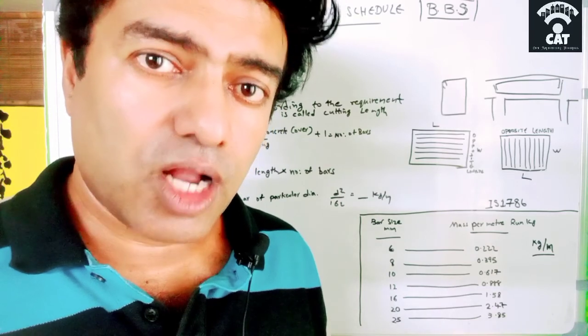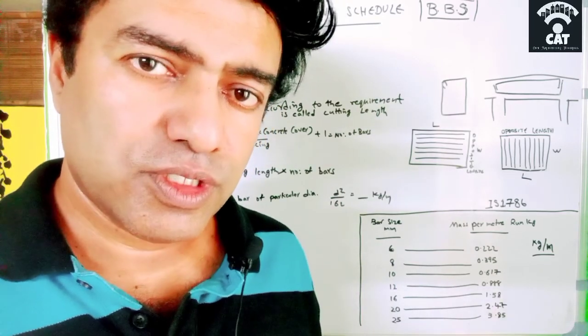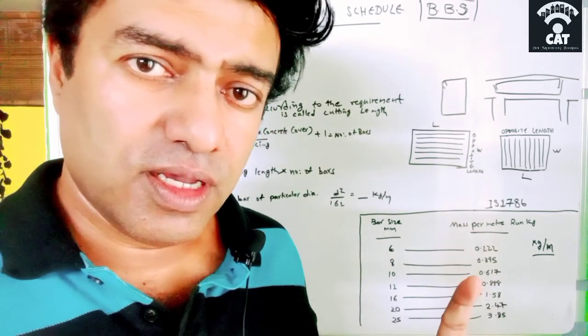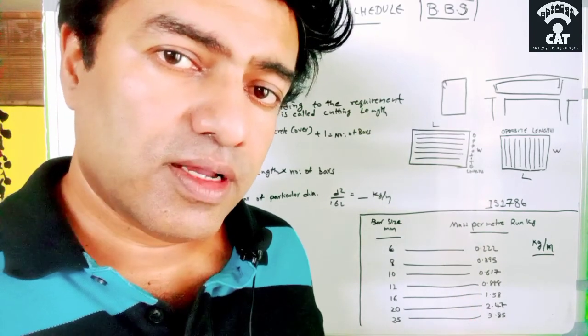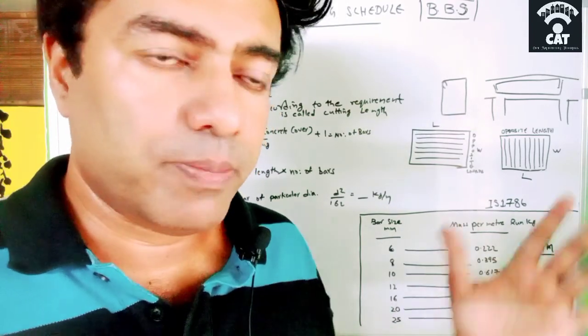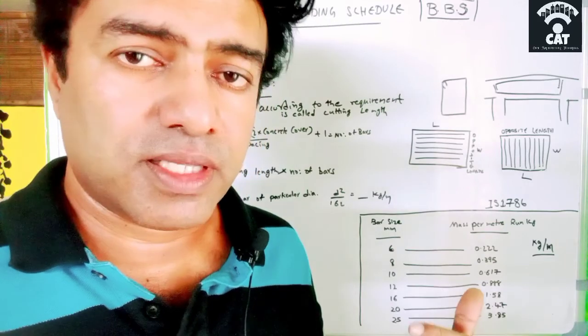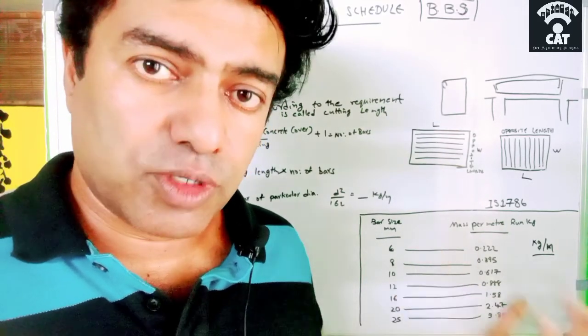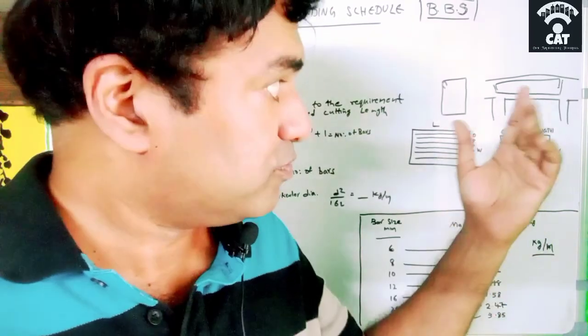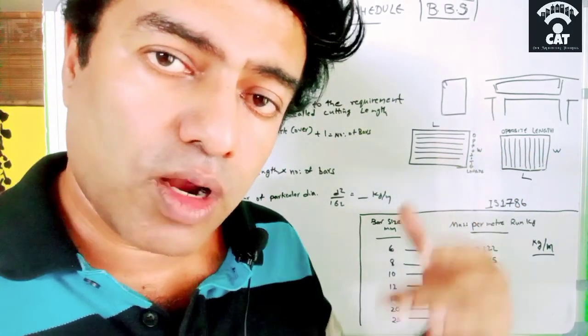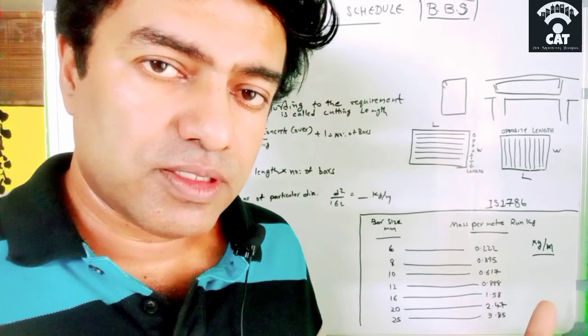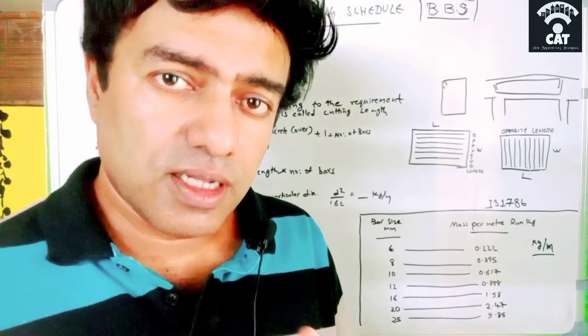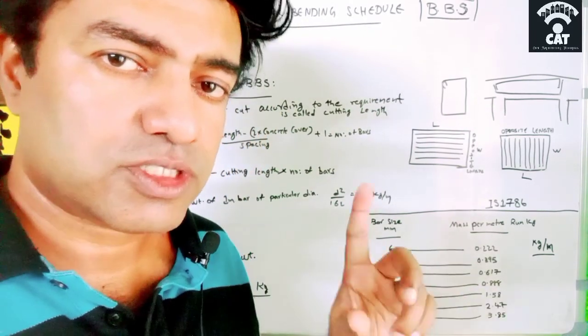We need to cut accordingly, according to the area of the concrete structure. It may be big, it may be small, and sometimes they need lapping, or maybe only cutting. If it is for a stirrup, you need to cut. If it is for a long continuous beam, you need to lap it. So the cutting length will be according to the structure.